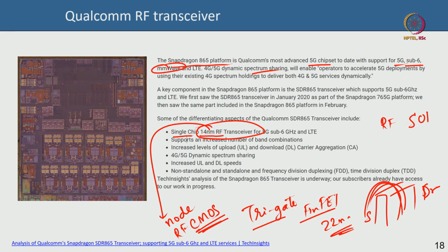So, you have a buried oxide layer to prevent that coupling, and then that oxide may have a trap rich layer to trap all these defects and carriers from dangling bonds etc. So, RF SOI may be slightly more expensive, but it is designed for high performance RF devices, and RF SOI can compete with even gallium arsenide technologies as far as noise is concerned, for instance. Okay, noise and linearity are concerned. But anyways, this is a Qualcomm transceiver IC that goes there.